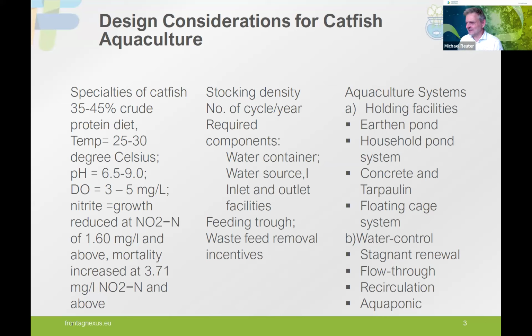And as I wrote, it's important that we look into every waste product that is produced by the fish and also the oxygen demand of the fish, and that we calculate the needed flow rate for every single substance and compare the resulting flow rates, because it's not always the same substance that decides which flow rate would be needed, because it also depends on the efficiency of the treatment devices outside of the rearing unit.